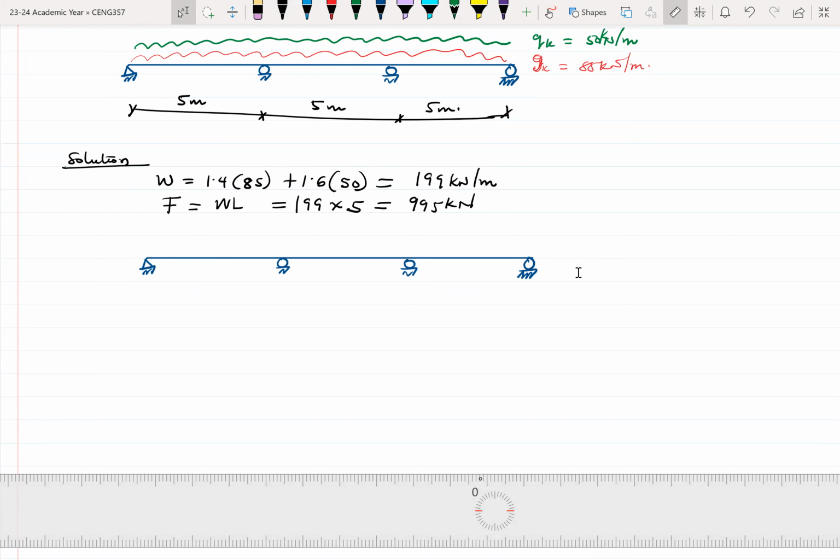So we know, in terms of the moment, M, this will be 0, this will be 0. Okay, at least from our previous computations. At mid-span, we get 0.09 FL. This is minus 0.11 FL, this is also minus 0.11 FL.